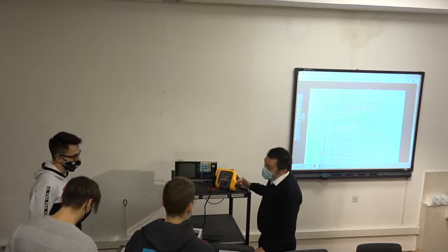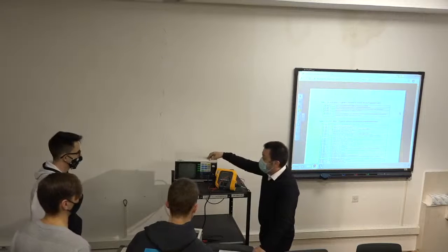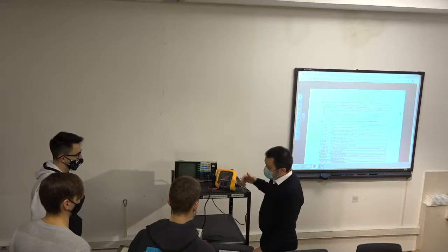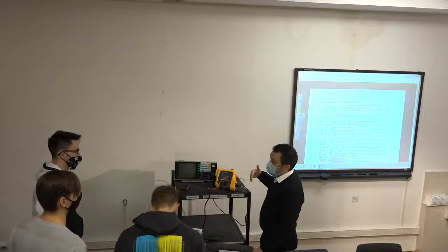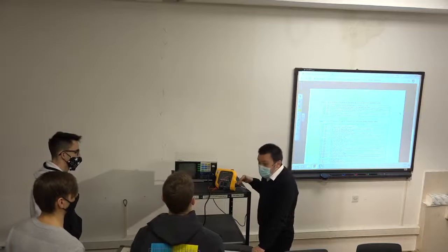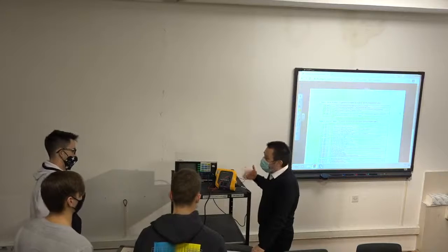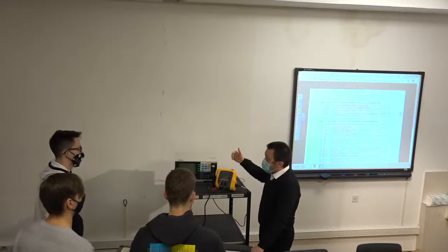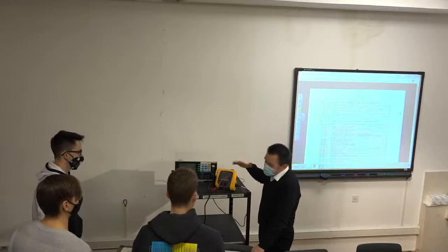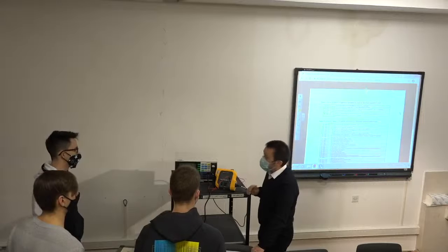So actually you start with the line, because if you are testing this device by connecting it to the analyzer, which is then measuring some potential differences and so on, if the mains voltage is not according to the standard, then you don't do the testing. The reason for that might be that you have a bad network, but since we are not in Africa or the Caribbean or something like that, we have stable current distribution, at least in big cities.